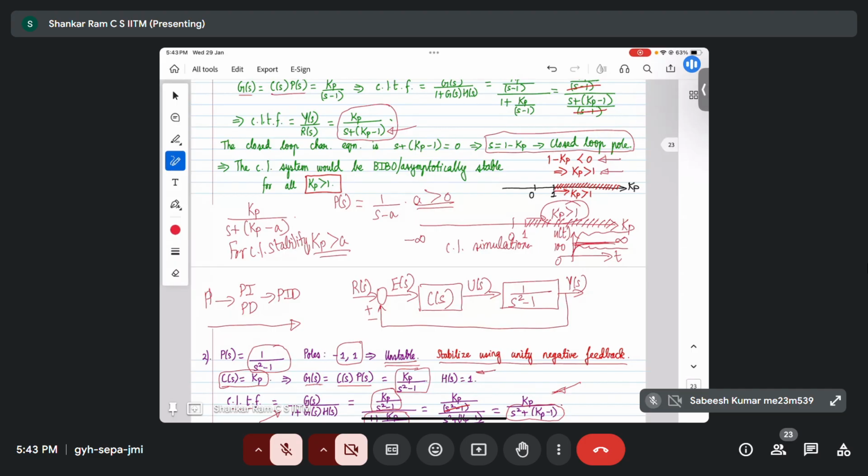And how many on the imaginary axis? That will in fact dictate how tough the problem is going to be or how easy the problem is. So the more open loop poles lie on the imaginary axis and in the right of complex plane, stabilizing the closed loop system is going to become more challenging.